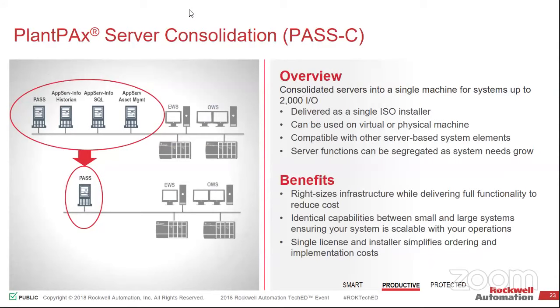So for anybody that's putting together a DCS process system, if it's less than 2,000 points of IO, we no longer have to separate out the servers to multiple. We can do everything on one box. And you can finally do what I always tell you don't do, which is put all the servers in one. If you guys are my system integrators, this is now a nice little development box that will be included as part of your toolkit. So keep that, because this is now going to be the demo that we always run to show you what the software looks like.